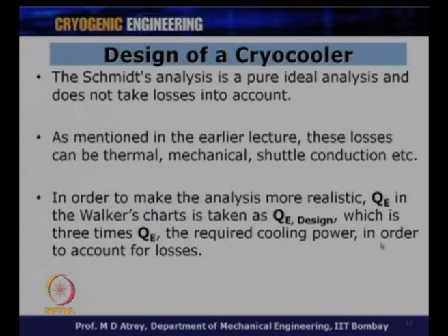The required cooling power has to account for these losses. That means I will design this cryocooler for 3 times the value of QE. What is required by me is only QE, but I will go for 3 times QE, which I will refer to as QE design. I will use this QE design value for referring to Walker's charts. So, QE design is going to be 3 times QE required.